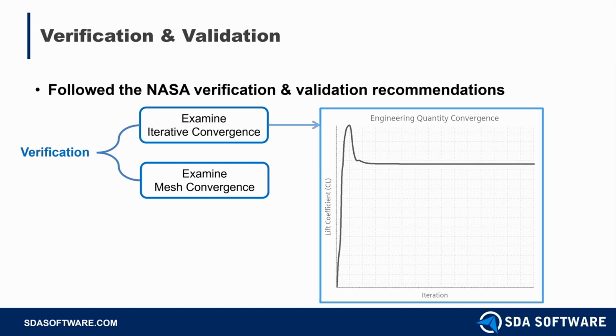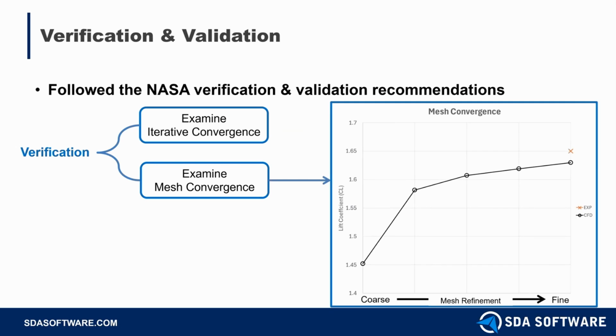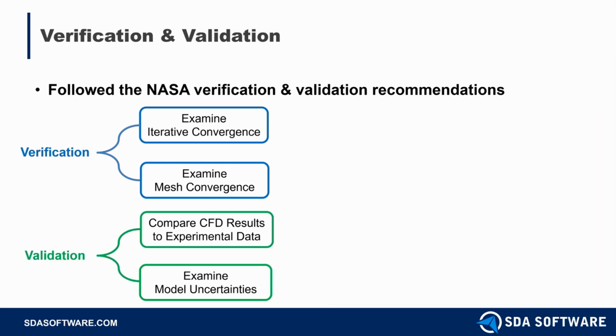And particularly for a mesh convergence study, we have 5 different mesh refinement levels, and we have predicted the asymptotic behavior at the finer mesh. And we can see in the graph that the finer meshes are well within 5% error bound. So we can conclude that mesh convergence was achieved with our processes. So we have confidence in the fineness of the mesh. And moving on to validation.